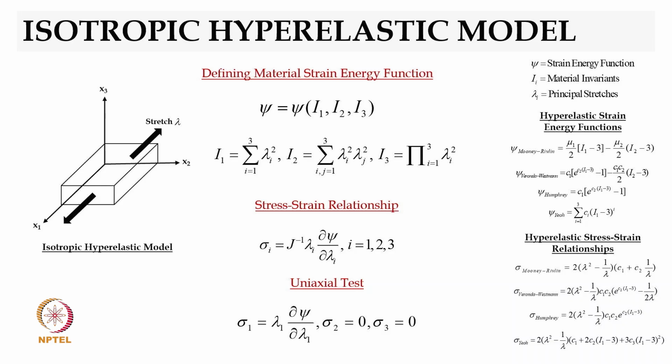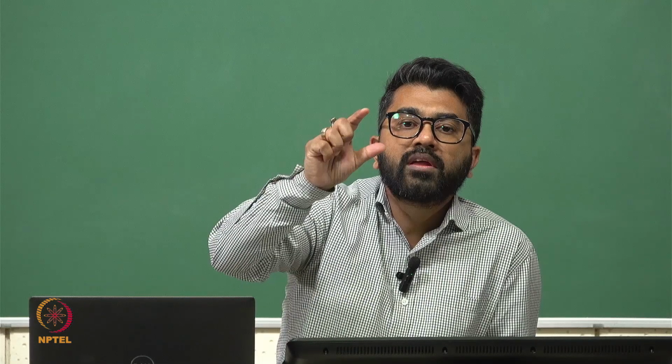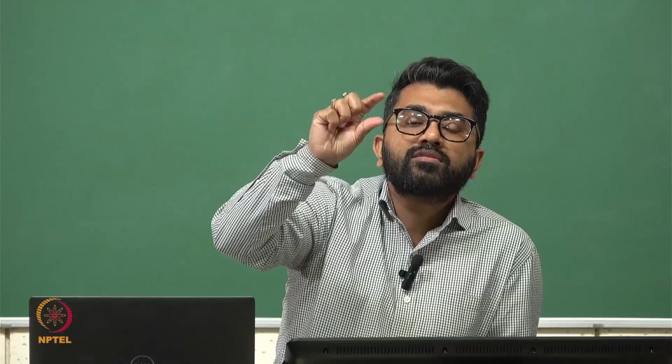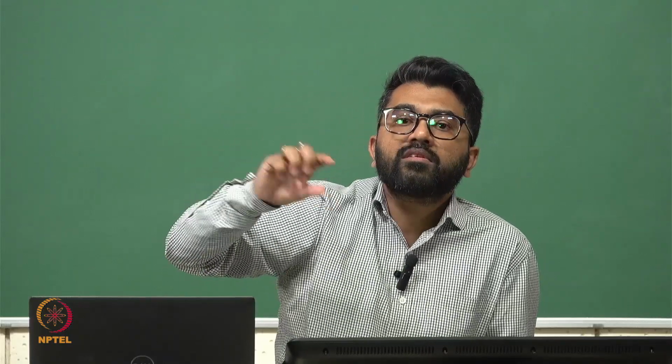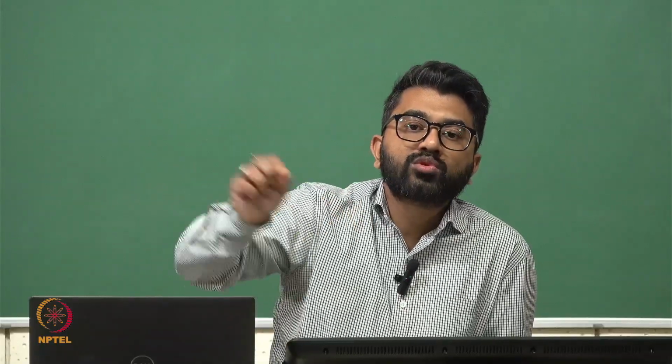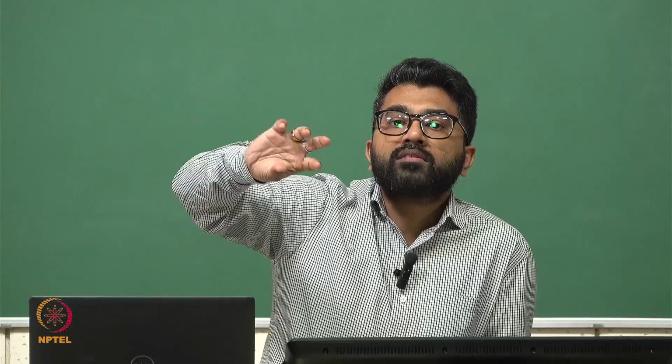But this left Cauchy-Green deformation tensor has certain parts which are known as invariants. Invariants mean these components in that matrix or tensor are not going to change irrespective of whether it goes through certain deformations, rotations, or translations. So if x goes to x1, or y is converted with a rotation matrix, these kinds of things do not change this invariance. You can read about invariance and tensors if you're interested.